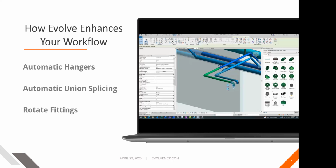Is there a way to schedule out product entry, hanger diameter, size, parameter in Revit? Yeah, you can schedule out your hangers and get all that information and pull it out. You can scope box and reduce your visuals so your hangers are showing. You can create hanger assemblies, and you can do basically a takeoff of what's in that hanger. And you can do that with custom families. Some families have that stuff built in, some don't.